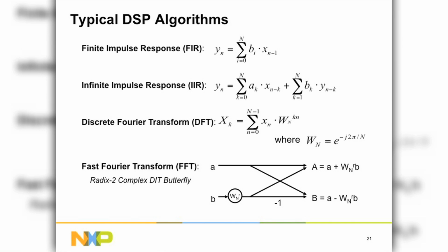And typically DSPs have instructions or features to do things like zero overhead looping. And so basically you don't have to reset the loop up every time. And they also have features to allow you to change your pointers and more parallelism, so you can actually fetch your data and opcode. The M4 doesn't have that.